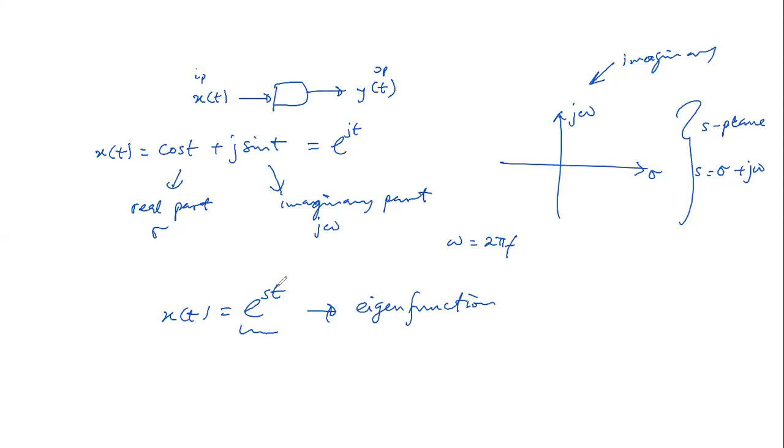So it means given an LTI system, let's say a continuous time LTI system characterized by some parameter h of s, the eigenfunction, which is the input to the continuous time linear time invariant system, is the same as the scaled version of the eigenfunction, where h of s in this case is also a complex quantity.